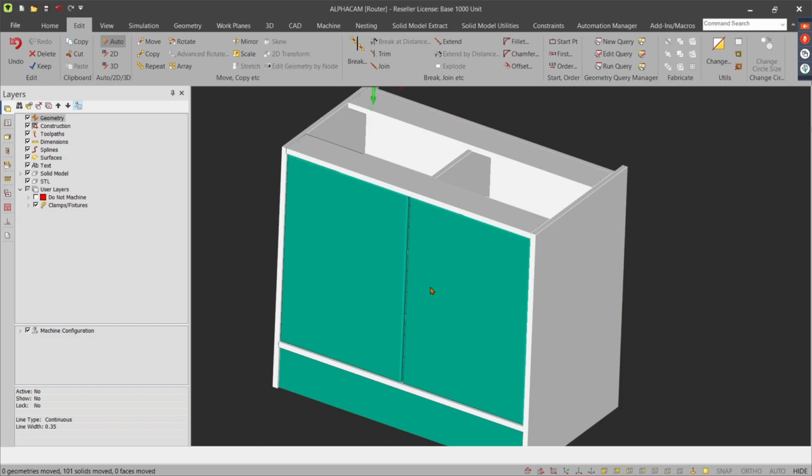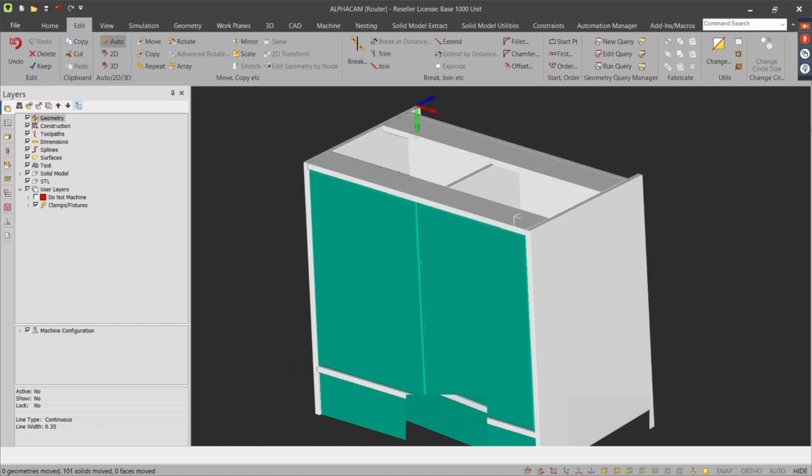And that workflow process from design to manufacture can be really sped up with the use of queries. We can take the solid model name, we can take features from the model. We can say if the model is over this size, delete it. If it's got no features, delete it. Stuff like that. So how would we then go about processing this?